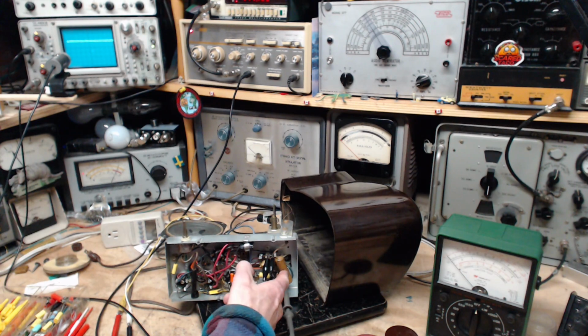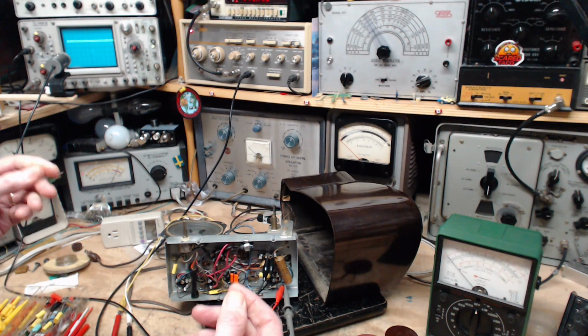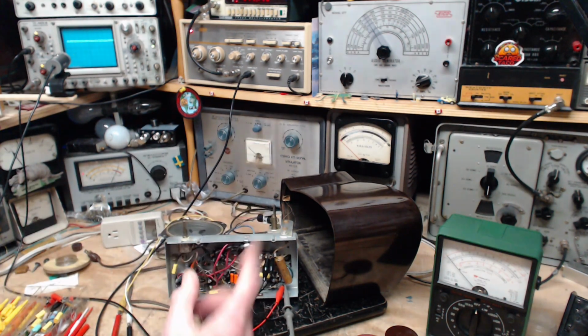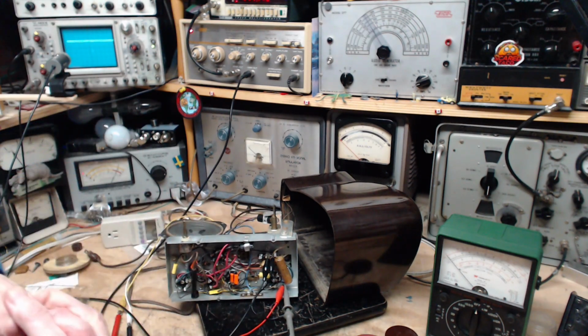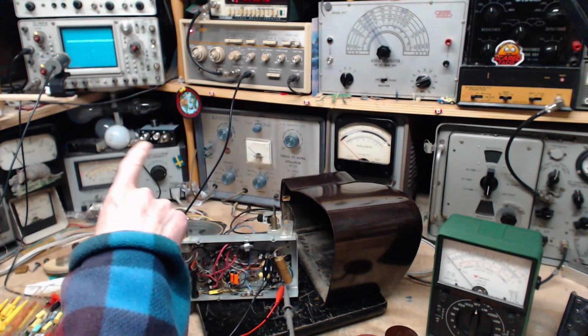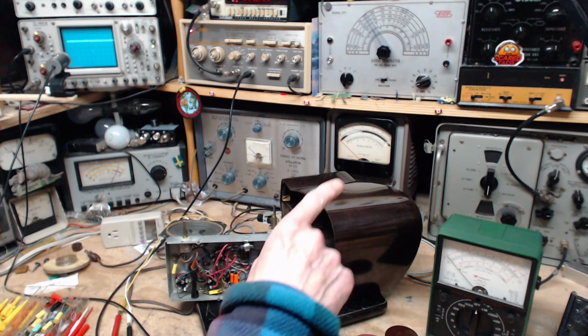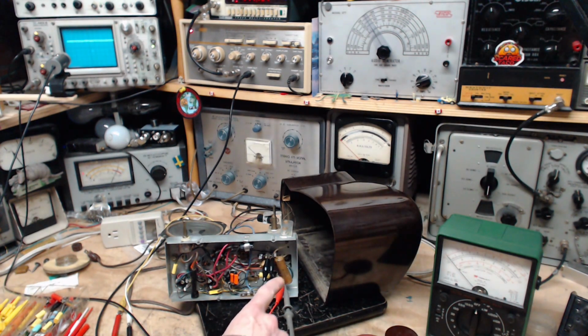This is supposed to be tuned to 455 kilohertz. It's a series resonant circuit. A series resonant circuit impedance drops at resonance. Parallel goes up, but in series it drops because the two reactive components cancel, and all you're left with is the resistance of the circuit. So we should be looking for a high impedance and then a drop and then go back up again like that. And this frequency will mark the tuning frequency of the capacitor.